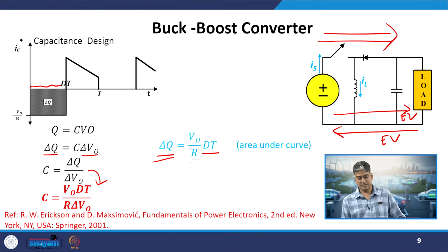So, we will have some excess energy, we can remove it and use it to recharge our battery, so that our battery energy will be optimized or we will have a longer range. Generally we operate our EV motors in the 4 quadrant operation mode, that is, it will be going for regeneration. Whenever I have excess energy, I can use that to charge my vehicle.